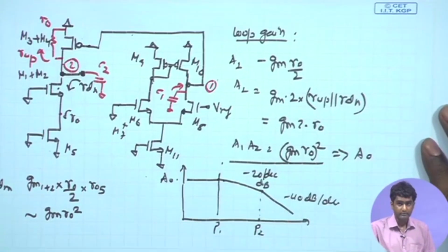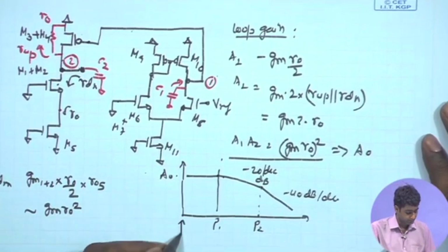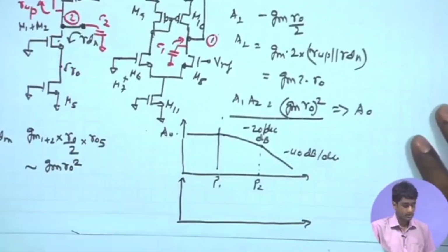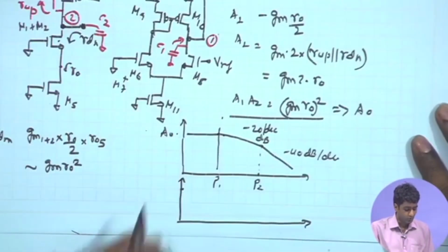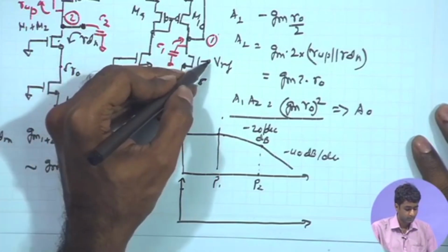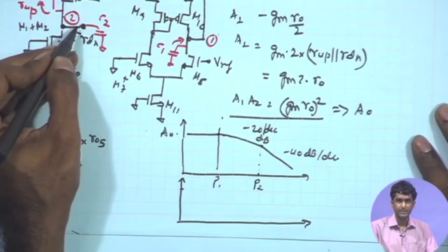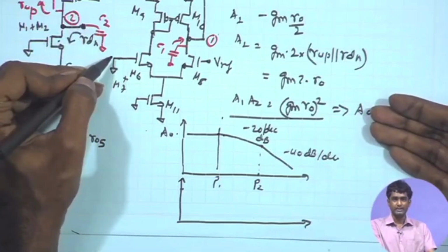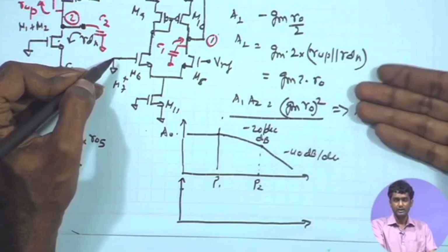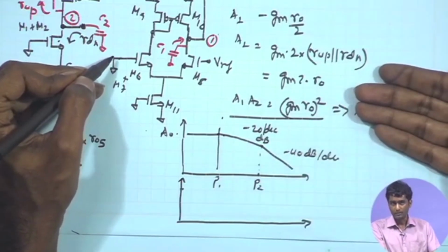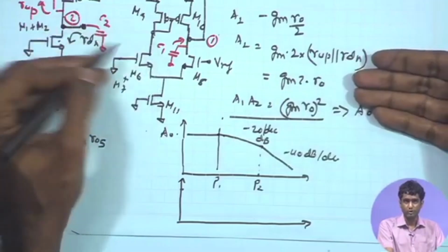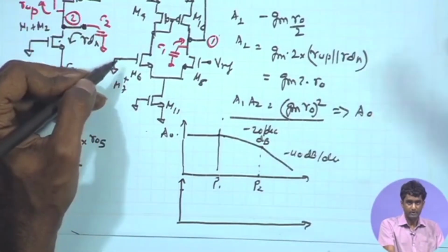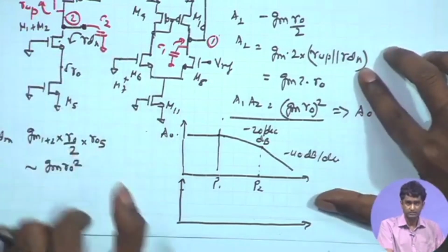And likewise, if we talk about the phase response, at low frequency we start with overall 0 phase. From input to the final output we have a 0 phase. Remember, there is a -1 term in the loop coming because the final output signal is applied at the inverting terminal. So, that gives automatically a -1 factor and hence 180 degree phase shift across the loop. So, effectively 180 degree phase shift is already available. So, we are keeping that as a constant factor.